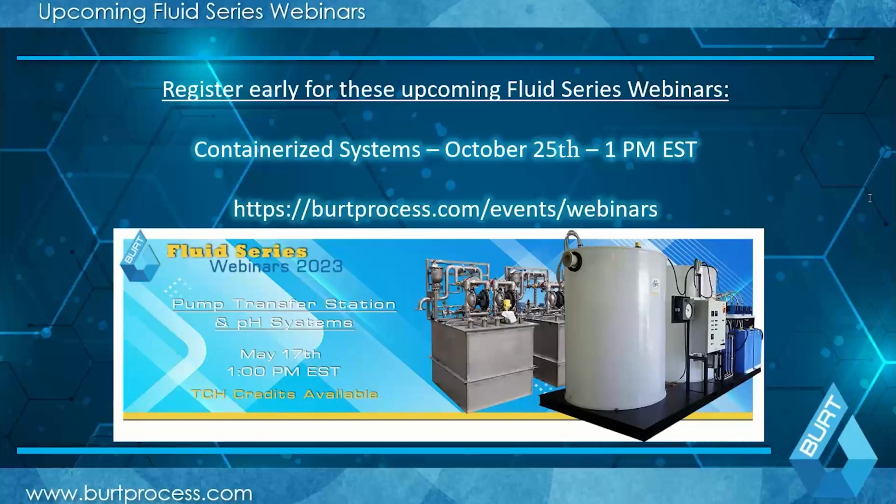One of the other questions we have here is, what would you recommend as far as the difference between using onboard reagent tanks or using chemical drums as part of a pH neutralization system? I get this question quite a bit, and the answer is it's really an owner preference in those cases. There's no way to put chemical into a pH system without some form of chemical handling. If you have onboard reagent tanks, you have to fill them, so you have to bring a drum or have a bulk storage, and then have a way to actually pump it into your tanks.